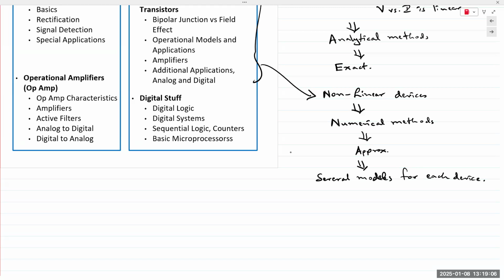For example, I might say that based on the circuit conditions, let me assume that the voltage is between 0.8 and 1 volt. So I would go through the solution. At the end, I might arrive at an answer of 0.6 volts. Then I would change my assumption a little bit, and I would redo my calculations. You would keep redoing your calculations until the final value fits within your assumptions.